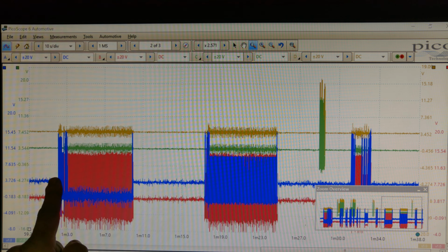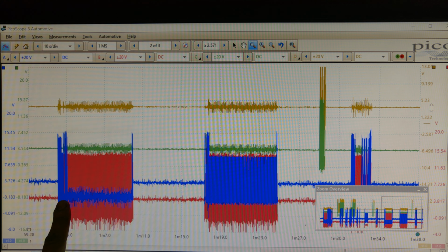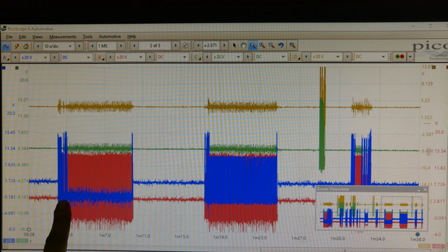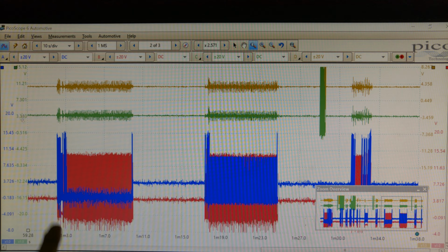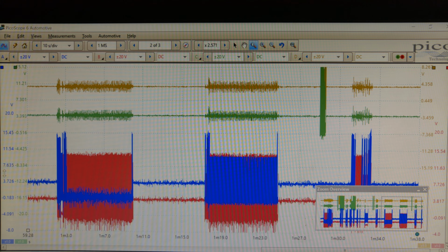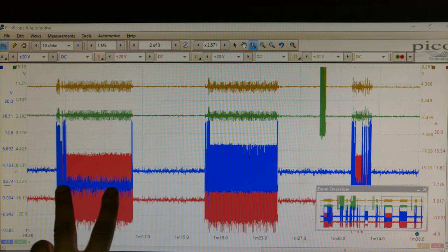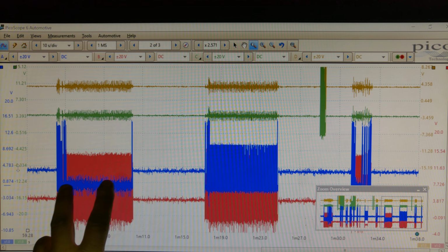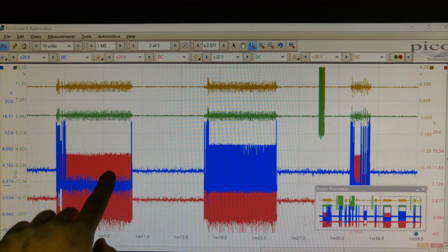and then I went to reverse. I'll just separate this line so we can see a bit better. Okay, and let's put the green one up top too. So red and green channel here, as you can see. As soon as I hit reverse, the red and green channels start sending power and earth to the actuator. This is the bottom actuator.